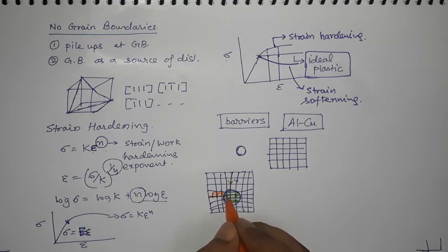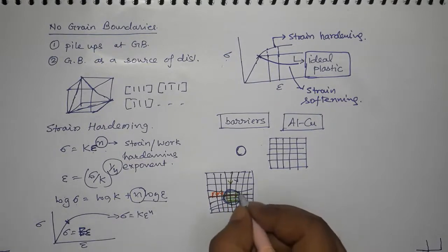A dislocation is just a line, the boundary between that extra half plane and the missing plane. So that boundary can still move in this zone and also come out of it. So this is one-on-one matching. This is a coherent precipitate.